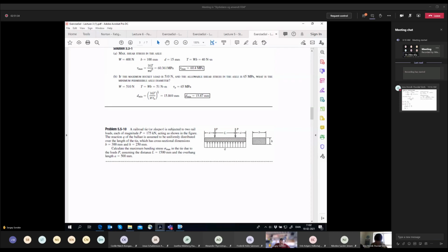Then you have this Mx with plus, and then the distributed load gives you the moment with minus, right? And then it must be 0. Then you isolate Mx, and you obtain, for x between 0 and a, that the moment equals qx squared over 2.